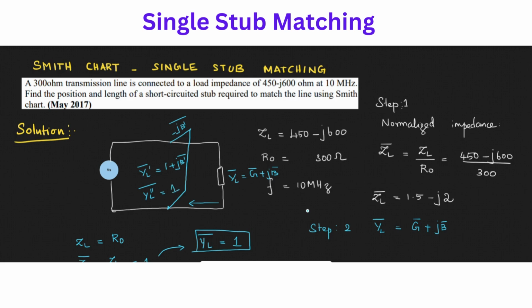So we can achieve stub matching, or impedance matching, here by converting our load impedance to a new value. What about this position? In this position, no matching is done. So there will obviously be standing waves up to your stub, but after this position, we won't feel any standing wave because the stub has been placed in the correct position and you will have only the incident wave. There won't be any reflected wave after this point. So that is the advantage.